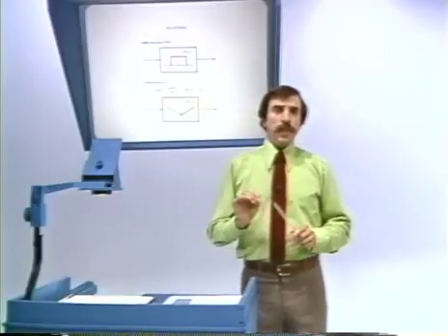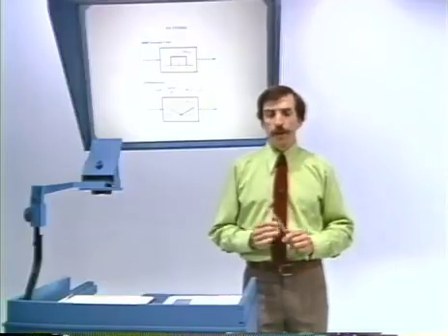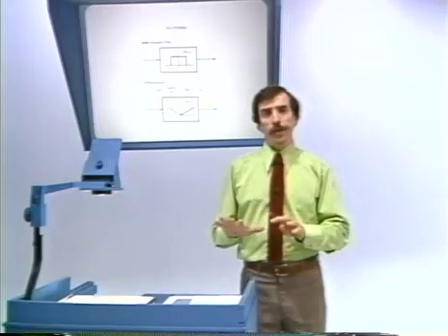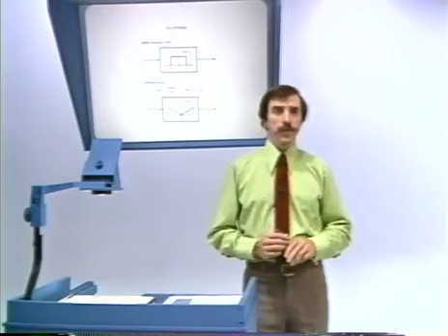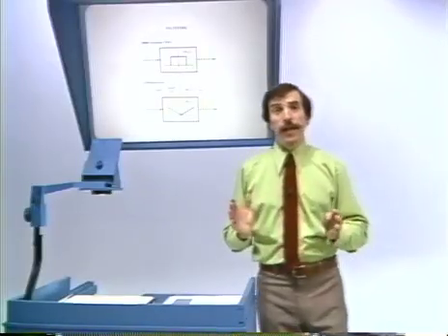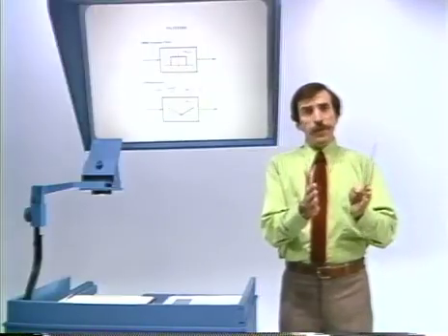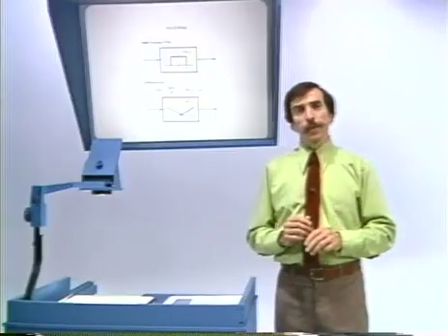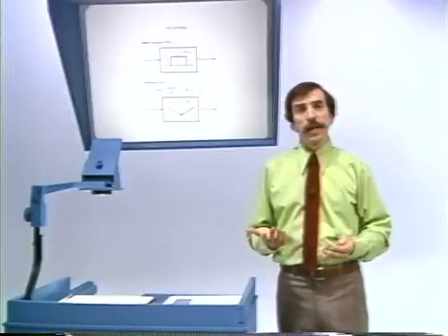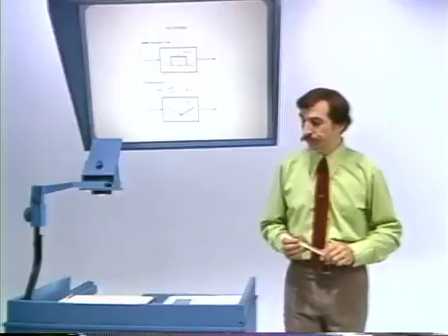Essentially, conceptually, what filtering, as it's typically referred to, corresponds to is modifying separately the individual frequency components in a signal. The convolution property told us that if we look at the individual frequency components, they get multiplied by the frequency response. And so what that says is that we can amplify or attenuate any of those components separately using a linear time invariant system.